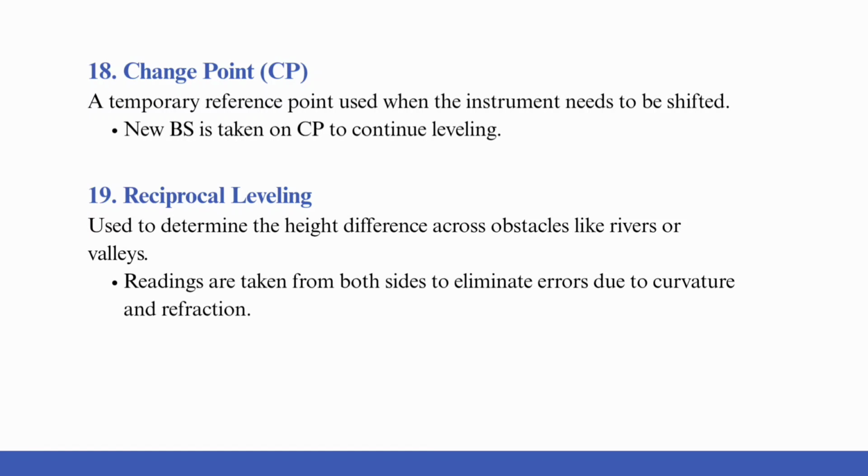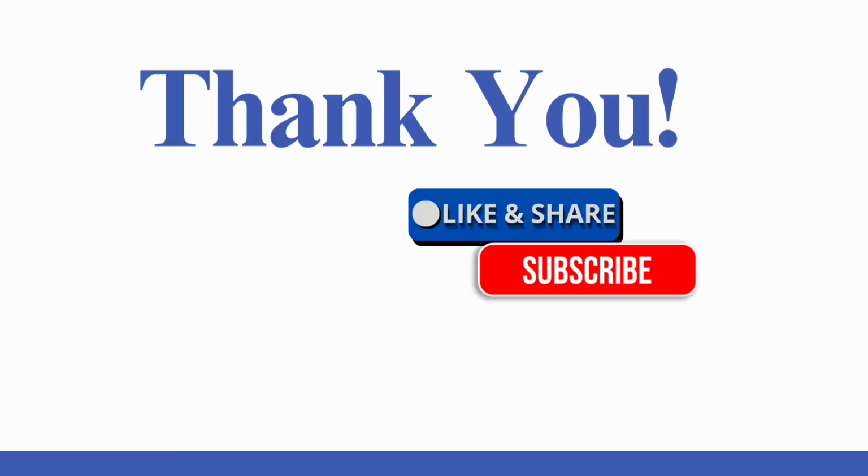Now the next point is reciprocal leveling. It is used to determine the height difference across obstacles like rivers or valleys, and the readings are taken from both sides to eliminate the error due to curvature and refraction. So this is all about the different terminologies used in leveling.